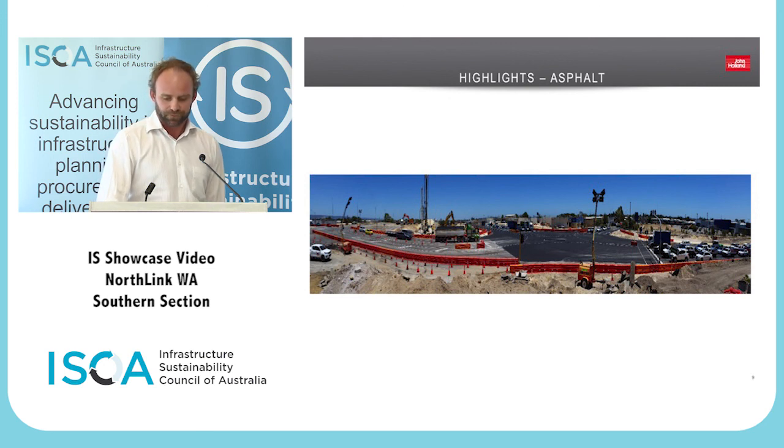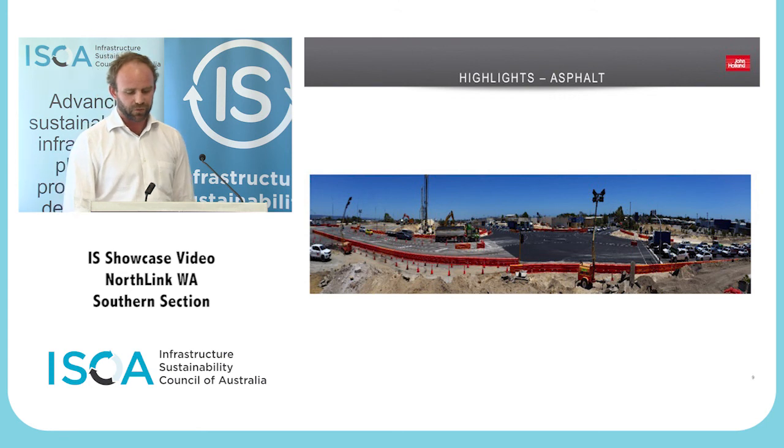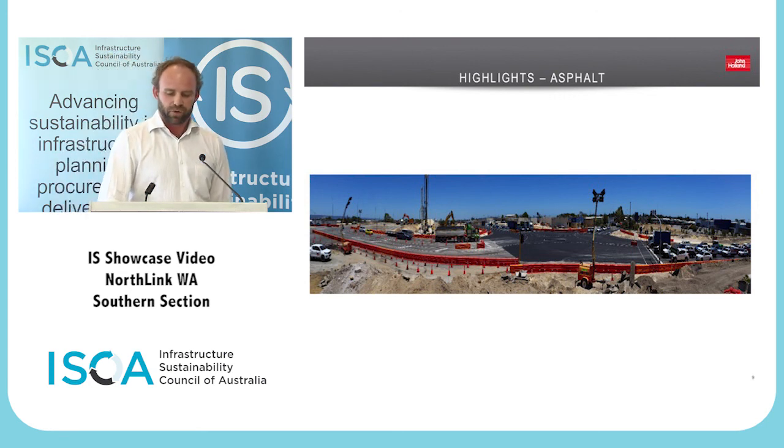Other things we did with the asphalt was we managed to incorporate a new kind of binder which allows the road to be stiffer yet thinner. We used one called a C600 binder, and that reduced the thickness by about 7%. That's incorporated across the piece. A similar initiative that we're piloting is the use of EME asphalt.